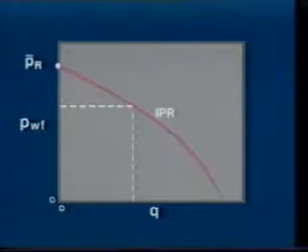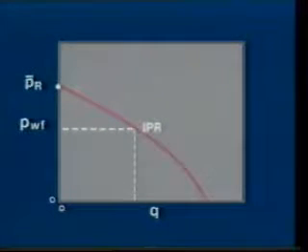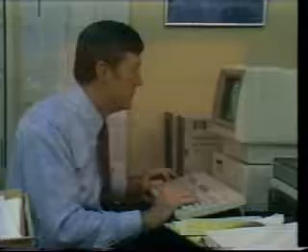Alternatively, if the flow rate is to be held constant, the bottom hole flowing pressure must drop continuously to maintain the flow rate. At some point, the pressure cannot be reduced any further, and the rate must drop. The inflow performance relationship is a unique description of the performance potential of an oil well.